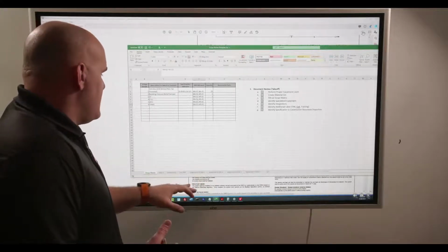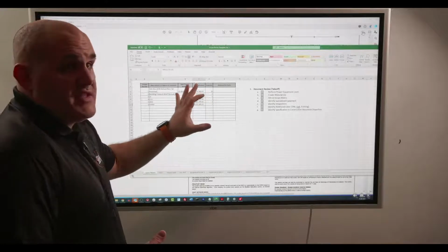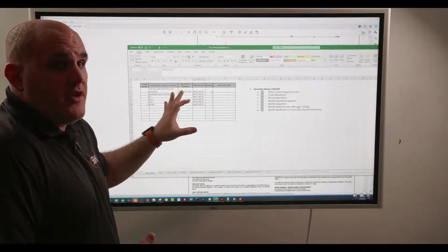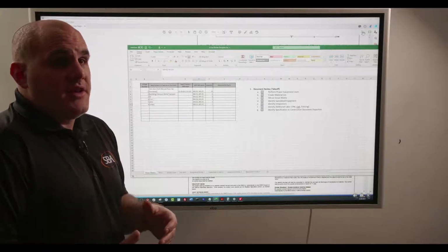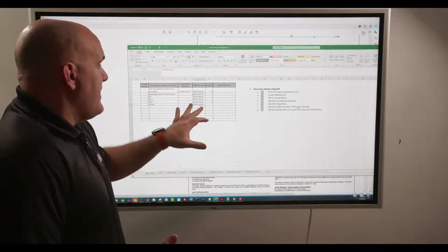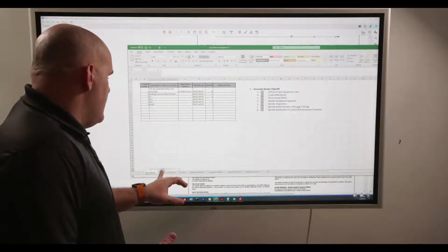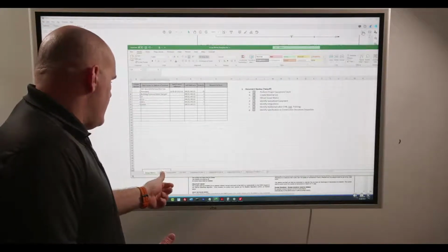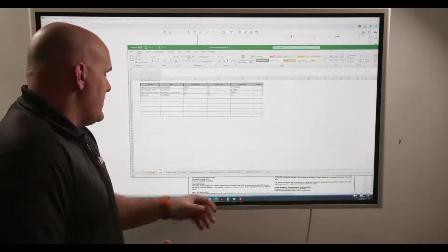So you do it off of CDs, you first list out your scope, you identify the MEP and spec reference. That's going to be critical when you're submitting your RFIs and RFCs, your requests for information and requests for clarification later in the design process. You want to have that documented, and then you move through and create your system level bill of materials for each system.